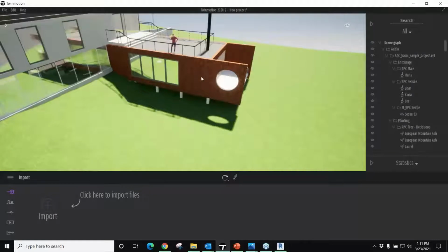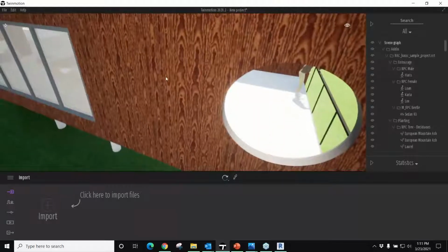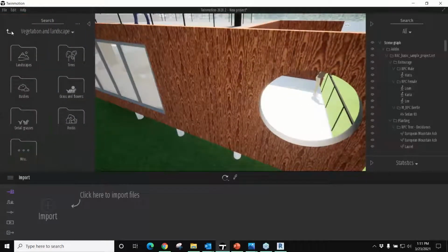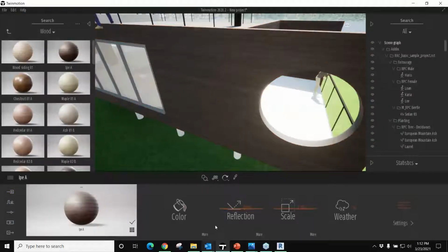In all of the material assignments that you do inside of Twinmotion, I like to use this wood grain, a terrible looking map that's on this wall here. I can replace this with the Twinmotion material, and I'll get through all the content and material stuff later, so just bear with me here, but we can replace this, change the settings for that material, and save this Twinmotion file.